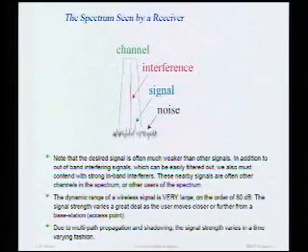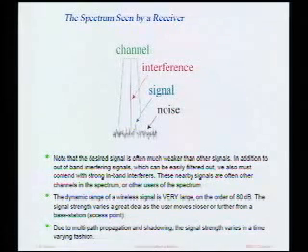Okay. The other issue that Al brought up was the dynamic range of the signals that we're receiving. You don't stand still and communicate, although there are point-to-point communication systems. Even in those situations, the signal strength varies. You might have to design a receiver that has to work over a few meters range to a few kilometers range. And that might mean a huge dynamic range in the signal that you're receiving. And I put a number here, about 80 dB, let's say, for a cellular communication system. This signal varies not just because you move closer and further away from your transmitter/receiver, but also because the environment over which you communicate changes.